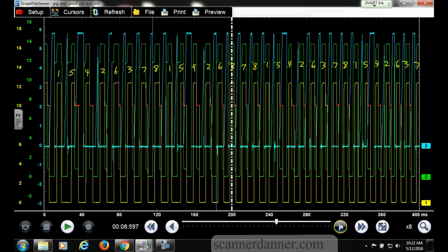Best I can do. Coil dwell. Strong power. What's that? So it's also strong power, like right after the first cylinder, and then it drains off. Yeah, exactly. And by strong power, I mean you can see the dwell time would be exactly that. We're holding this coil charged for, I think, too long of a period of time, and it's affecting the one right after it for whatever reason. It's doing that.